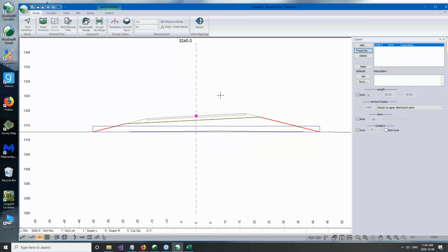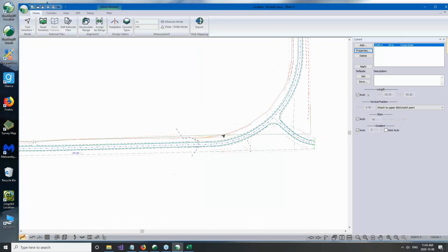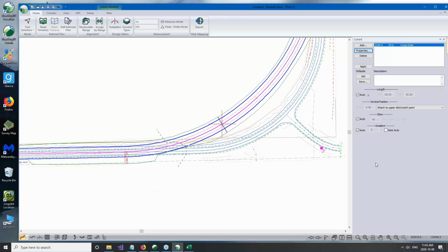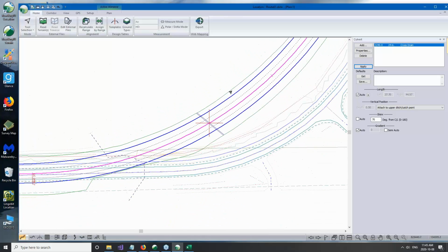There's my culvert, and now looking in plan view, I should see at my station, there you go, you can see the culvert that I've created. I could also skew the culvert so it follows the actual, there we go. So there's a skewed culvert at that station. There's a few other things. You actually can model culverts as separate alignments. You can also put in bridges. Basically a bridge is a section where there's no cut or fill. I hope that answers that question. Yes, it certainly has.